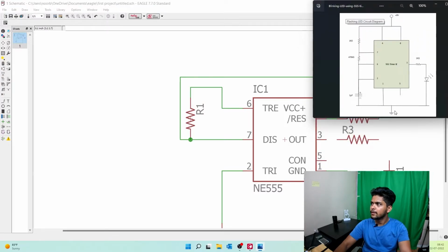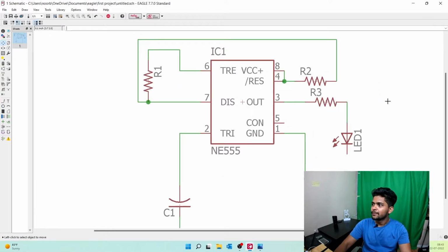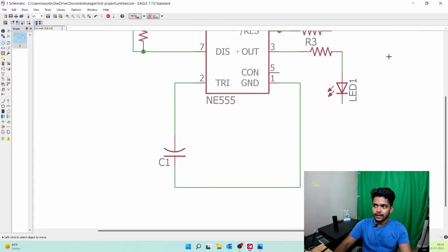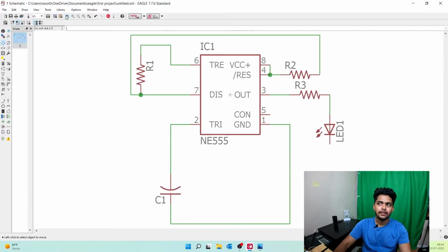Now in the circuit, if you guys can remember, it is down, correct? We need to correct the polarities correctly, guys. Anode and cathode, that's important. So let's go to wire and start wiring it. See, again there is an angle. So set the angle back to 90 degrees, escape. Now, as this is connected, here we need to place ground and power supplies. Let me fit the screen.